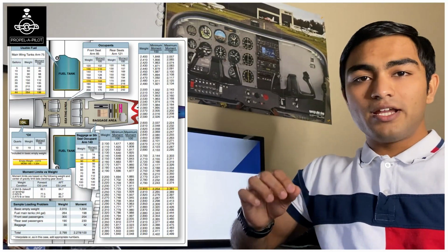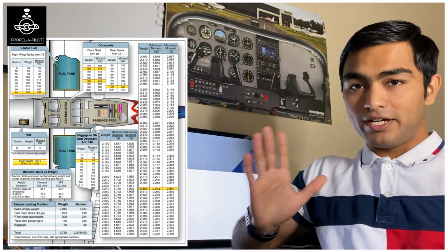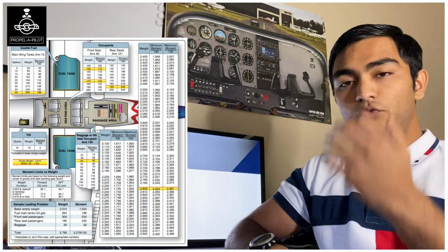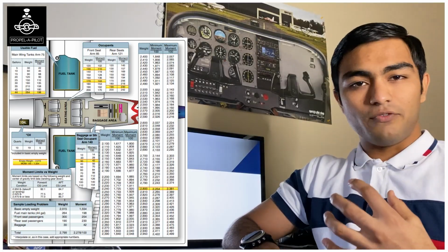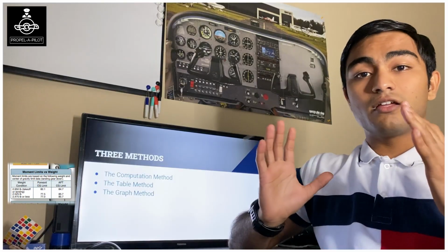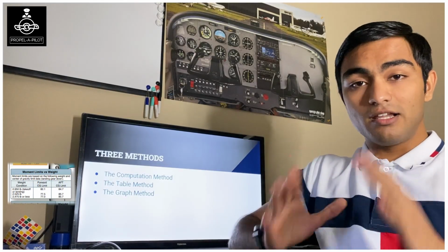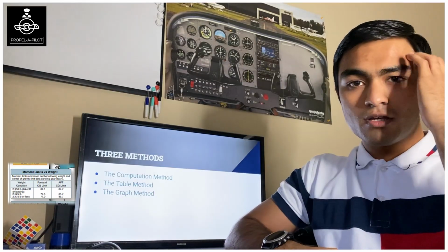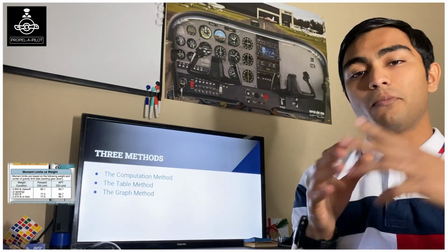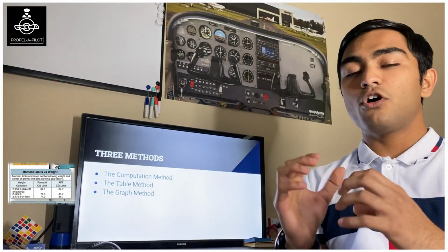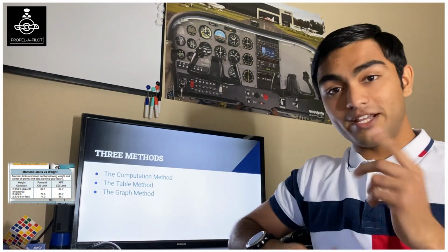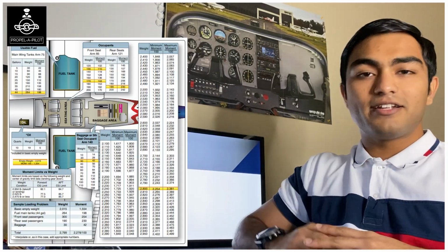Then look up the weight for each item in the appropriate table and read the moment given for it and note it down. Once you are done writing all the weights and the moments, calculate the total weight and then read across between the moment limits table to check if your moment is within the limit for the given weight. For example, a particular weight will have a certain limit of moments from a maximum to a minimum moment limit. Your weight and moment should be confined within these limits for that weight. If that does not happen, you will have to rearrange the load.